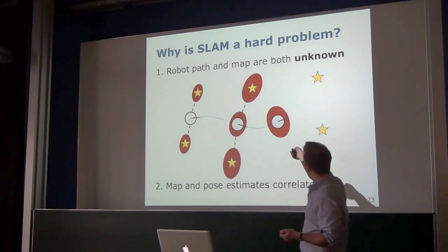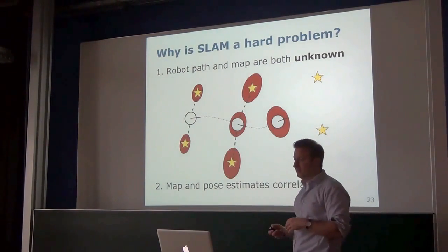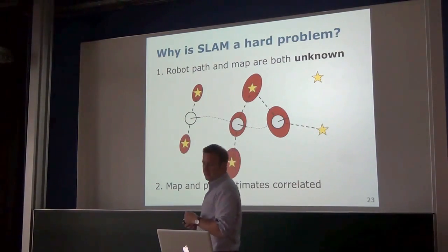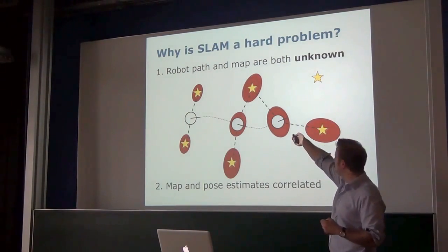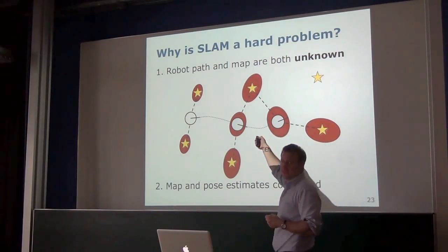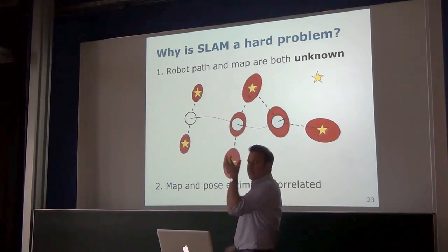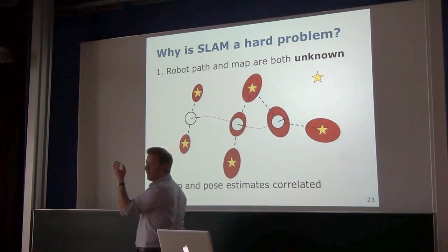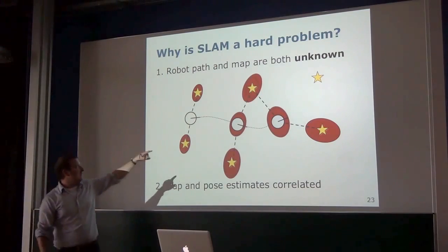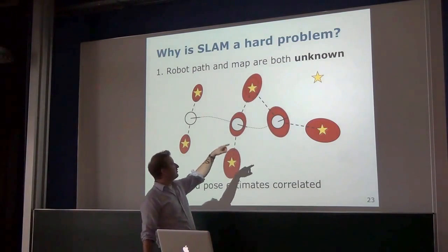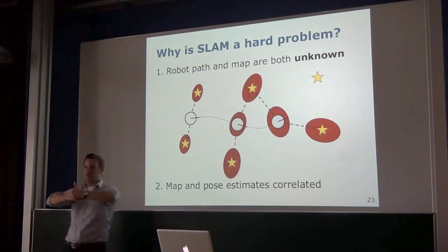Continues driving. The uncertainty again gets bigger. And then the interesting part happens, that it actually observes a new landmark, and it also reobserves a previously seen landmark. And now it already has an estimate of where this landmark should be, according to its previous observations and where it is right now, and as a result of that it can actually reduce the uncertainty.